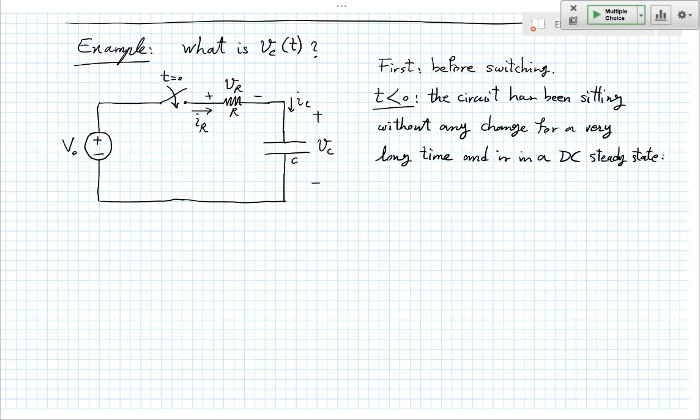Well, this is not a very difficult circuit to solve. How many nodes do I have here? Well, let's count. I have a node here, one node here, one here, one here, and one here. 4 nodes. So I get 3 KCL equations, 3 independent KCL equations. Mind you, they are very simple and straightforward.